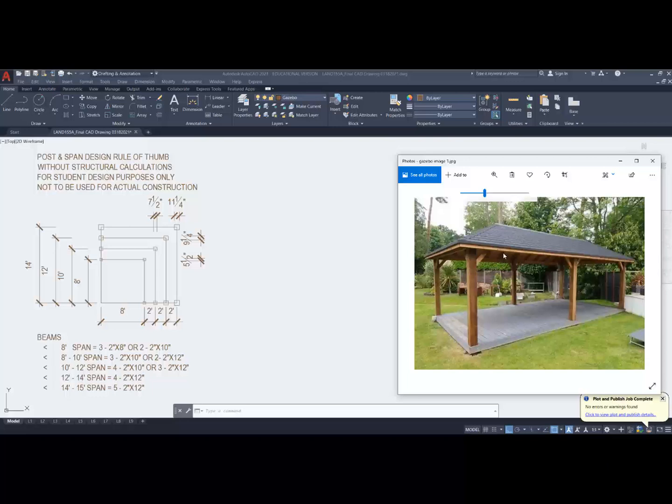So you can just take a look in there. You can see the actual rafters that come down over top of the beam. And the post itself is usually designed size-wise based on the size of the beam because it must be able to support the entire width of the beam. You can see here we have fairly large gaps or spaces. So the center-to-center distance here is what I'm calculating. And I've got 8, 10, 12, 14. And the dimensions I've given here are 8 feet or less, 10 feet or less, and so on. And I've specifically designed the post size so that it will actually be able to support the beam sizes.